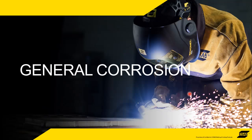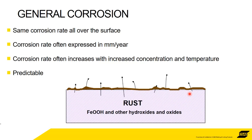So moving on to general corrosion, this is iron oxide. It's the red rust that you see on a car, on an iron bar, on an old gate. The thing about general corrosion is that it operates at the same rate all over the surface. So what happens is that the iron in the steel, or the iron, oxidizes. So it reacts with oxygen.